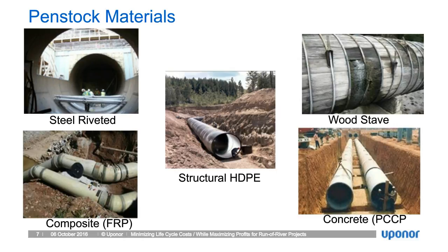Wood staves, again, very inexpensive, but the downside is that wood doesn't have a very long life cycle. One of the challenges is that when wood is saturated, it will not decay or delignify. The issues are if you have to shut down the penstock and dewater, that's when the penstock starts to degrade. Wood is, again, an inexpensive material, but it doesn't hold up very well to transient pressures, movement, and it does suffer from delignification from attack from the outside. So with a lot of wood staves, if you see pictures, you'll see a lot of leaks occurring from these.